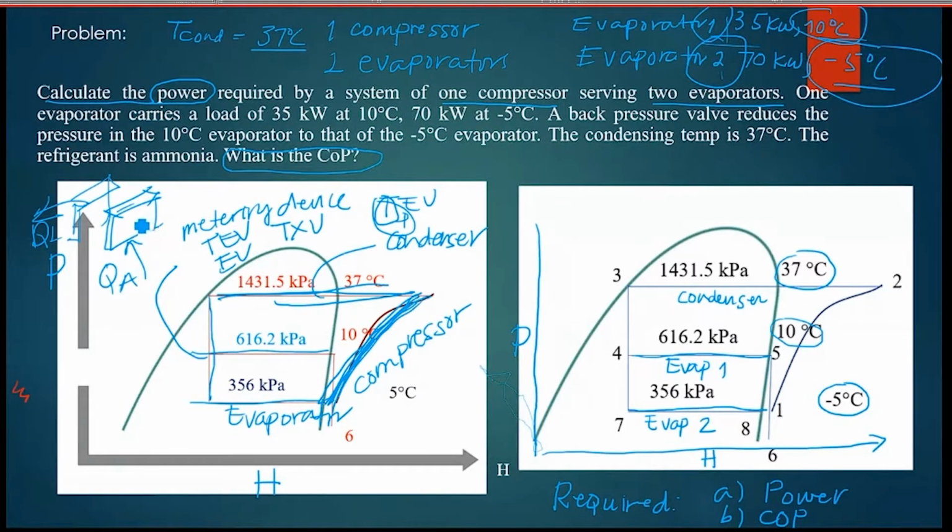But if you open the window or box type, there is this kind of thing, a bulb, like a thin sensor. Once it receives the temperature, it will register. Then it will change the opening of the expansion valve to allow the proper amount of refrigerant going to the evaporator at a lower pressure.